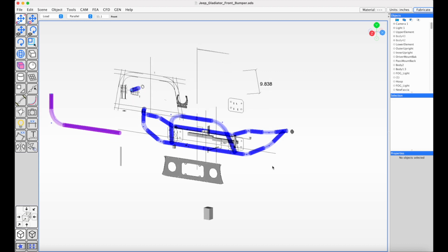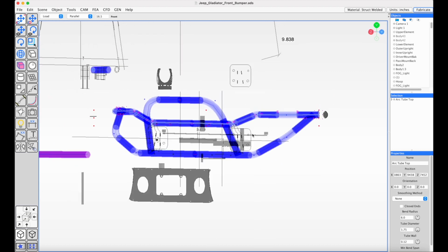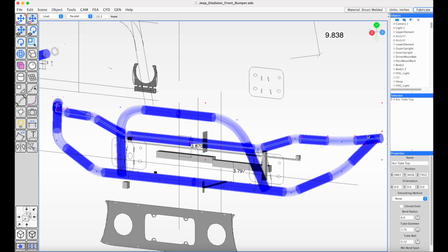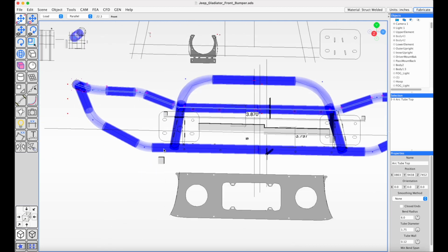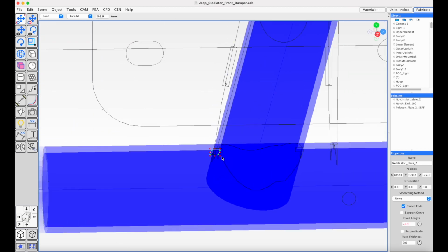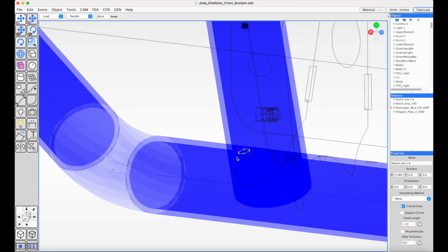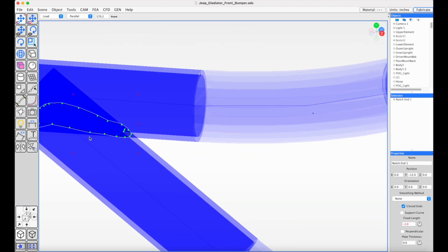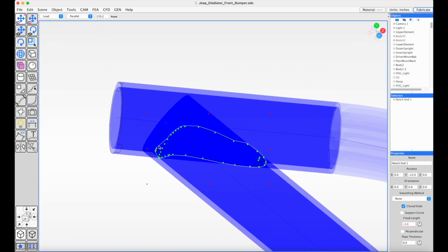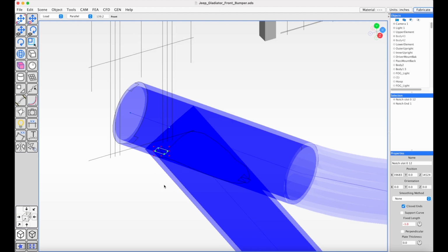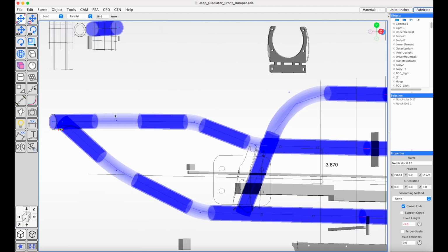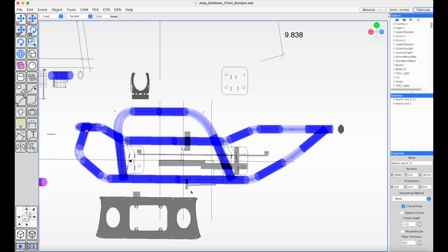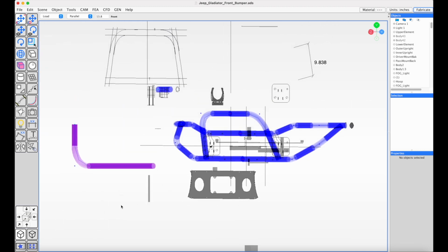one of the projects that we're working on is this Jeep front bumper. So this product has tubes that are about 6 feet long. This one has 6 bends, this one has 4 bends, and they are all fitting into tabs and slots. And the parts that we get are to a millimeter exactly what we want. You can see the notch profile here. You can see the tabs, and then a slot, and having 6 bends and then have the parts fit together is exactly what we wanted. So that's an example of what we can do with arc tubes.